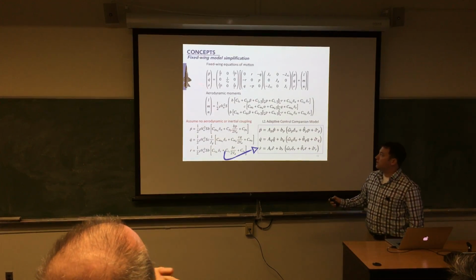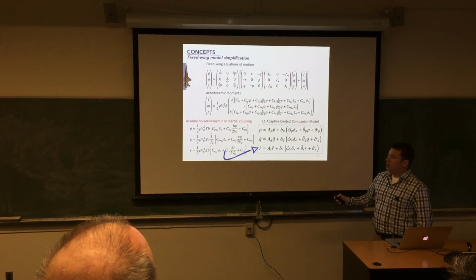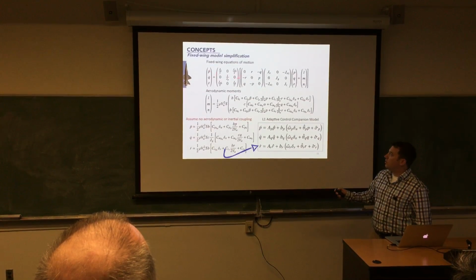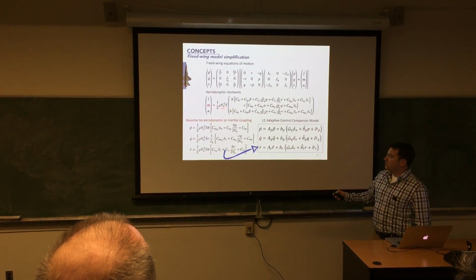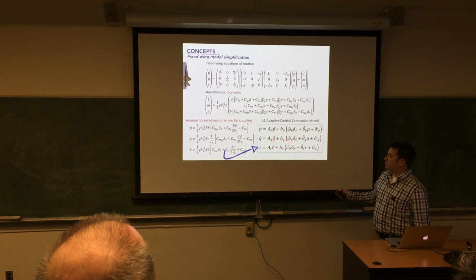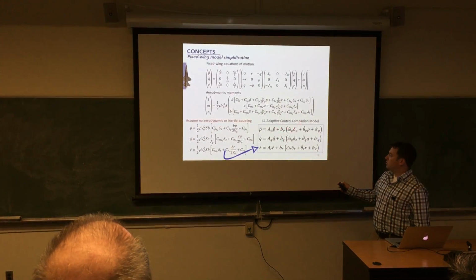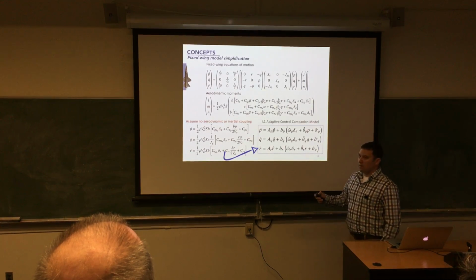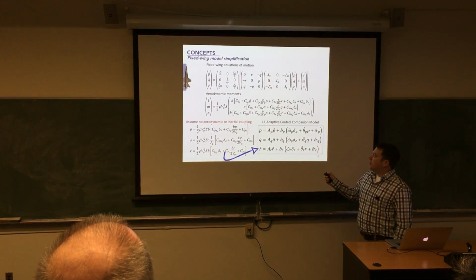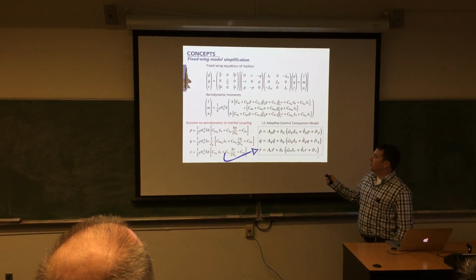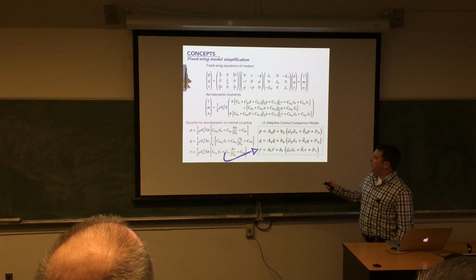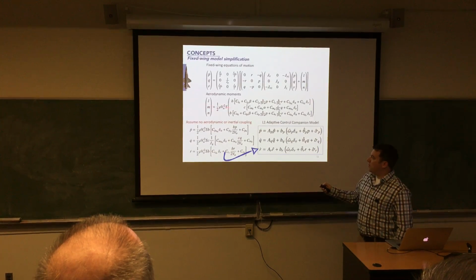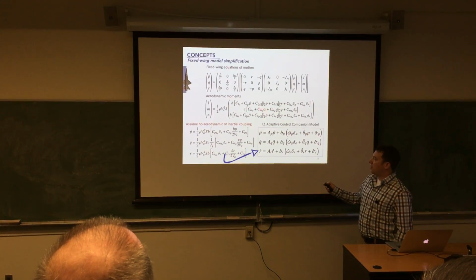So starting from first principles, I took basic aerodynamic fixed wing equations of motion, and also the aerodynamic moments, to reduce back into what the L1 adaptive control companion model was, established through the mathematics. One thing I wanted to point out here is that the fixed wing inertial tensor is non-symmetric, so there is inertial coupling. And your moments are also coupled across axes.